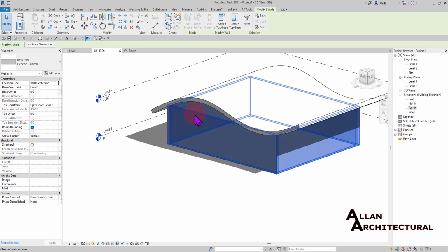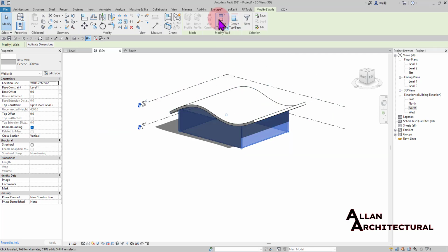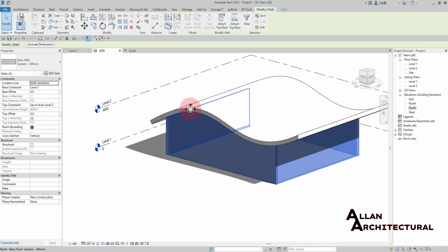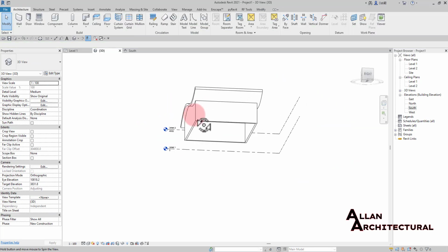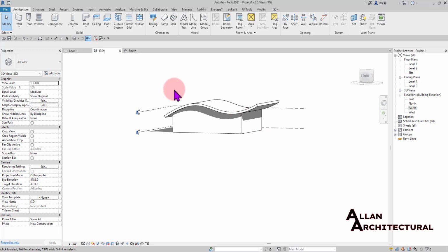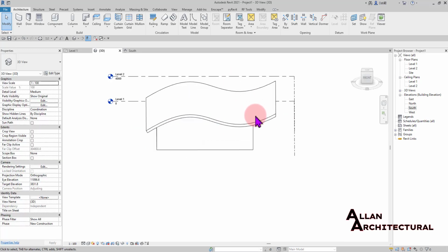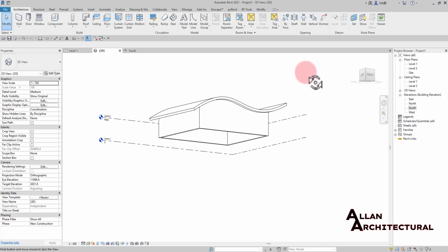Then you just click on all those walls in there, and then you select your top base in there, and then you attach all of that to that roof in there. So we have this in here, which is going to attach to all of those roofs in there, which is perfect. So now that's just one thing you need to know about this roof extrusion tool in there.